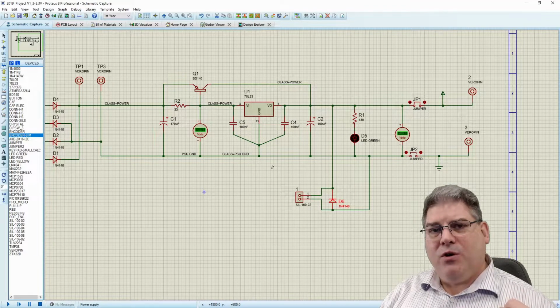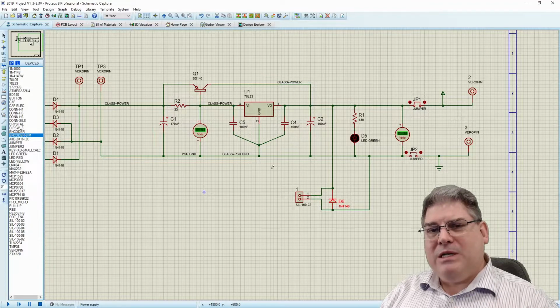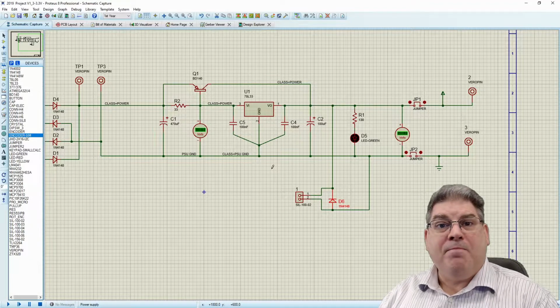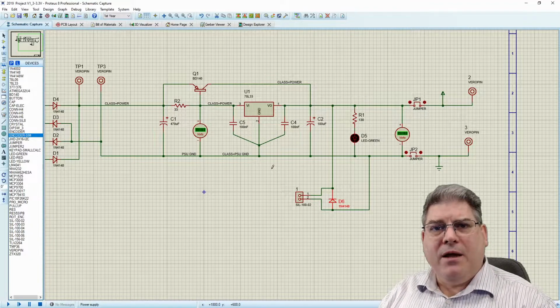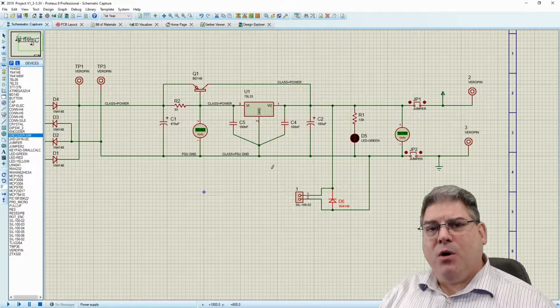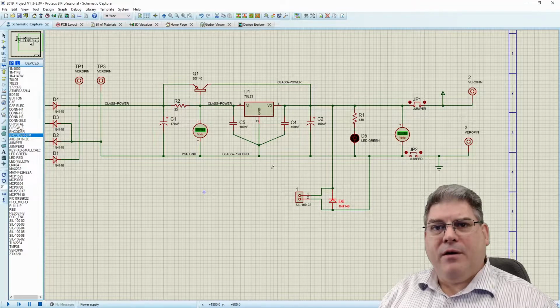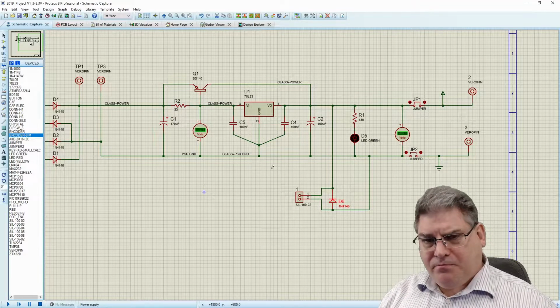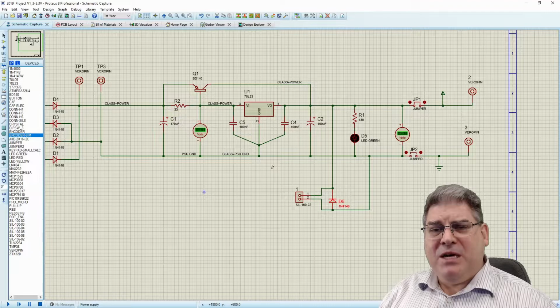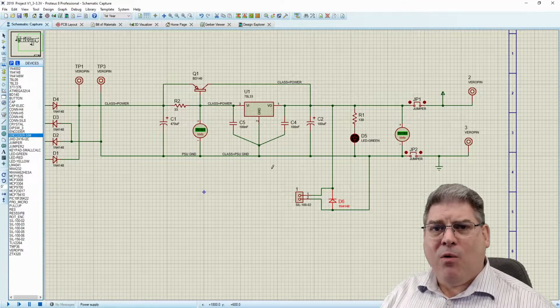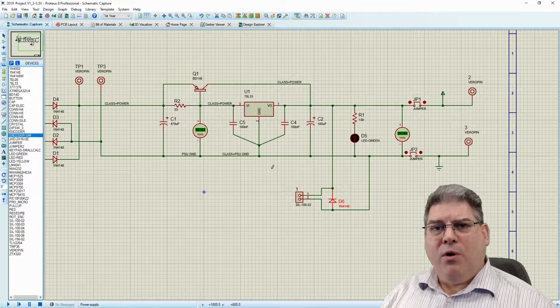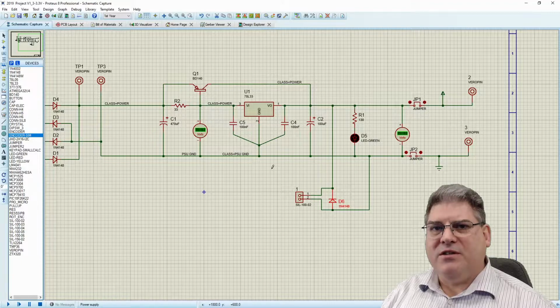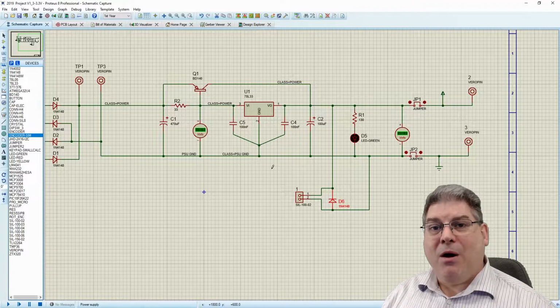So if we took our 12 volts at 1 amp and stepped it down using a buck regulator, we would change that to 1.2 volts at 10 amps. Things like FPGAs that require a lot of power now benefit from this low current right up to the device, and then very short high current traces to the power pins.